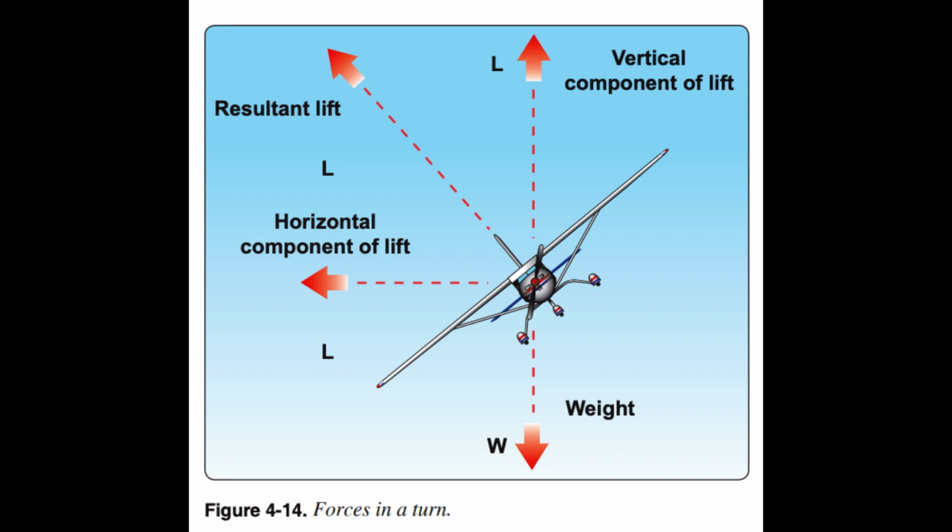In addition to the need for more precise airspeed control, the pilot normally changes the aircraft's configuration by extending landing flaps. This configuration change means the pilot must be alert to unwanted pitch changes at a low altitude.